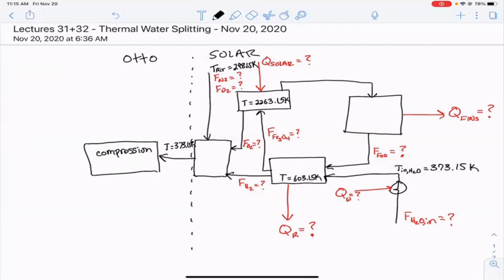And we were told that we are going to assume that it is adiabatic and reversible, right? Or delta S is going to equal 0. Now, of course, we're going to have to do some work, right? So we're going to call that WC1, where C just stands for compressor. And I know there's only one compressor, but that's how I chose to name it.